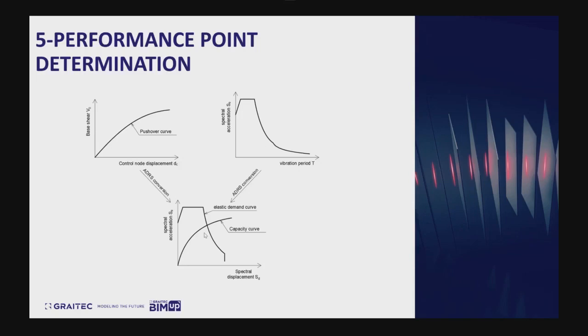This point is called the performance point. It is not directly this intersection point, because here we have what we call the elastic response spectrum, which is the elastic demand curve, but in nonlinear pushover analysis, since the plastic hinges have formed inside the structure, these plastic hinges will dissipate more energy during the earthquake.